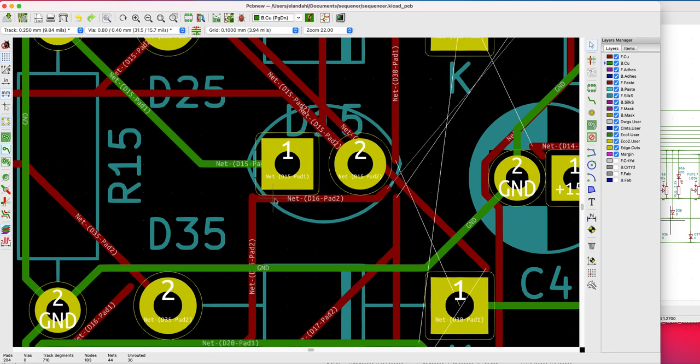But as we look here, there's a break in the wire, right? And then there's a rat's nest that continues from this position. So this is an attempt where we got a little bit too crazy clicking away, and we tried to make KiCad do something which it didn't want to do, which was you can't connect this red wire to this one or any others up here because we'd have to go through this wire, which is a different connection.